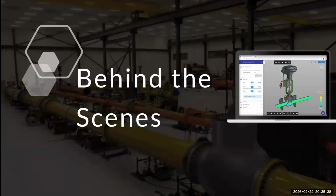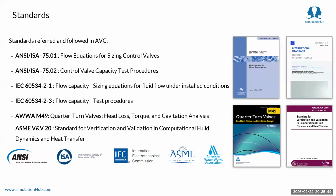It looks simple, right? But what happens behind the scenes? Does it follow all the typical CFD process? Yes. So what happens is we refer to all these standards in order to calculate the flow performance parameters, as well as the methodology, the simulation flow conditions and pressure tappings, all these things we refer to these standards. And also there are some verification and validation guidelines we follow.